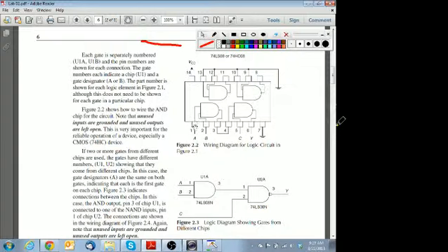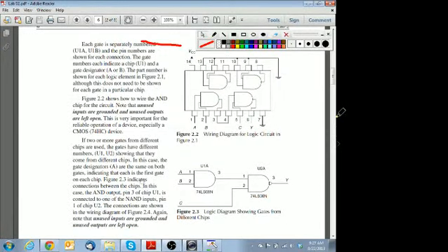So the only information they're not telling you down here is where the power pin is at and where the ground pin is at. That's one thing that you typically have to know, or get the data sheet to know what that is. Sometimes they will have a separate place in the schematic that has it. Actually, a lot of times what they do is U1A, the A package, which is right here.